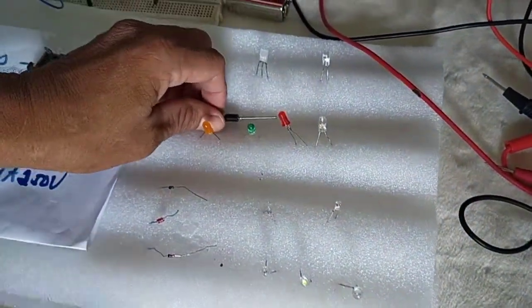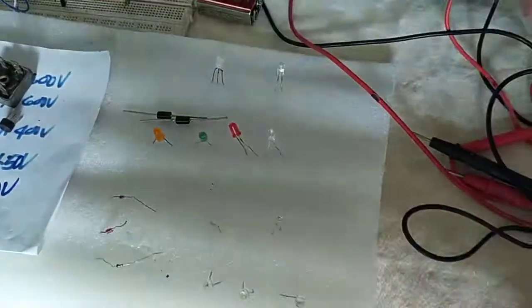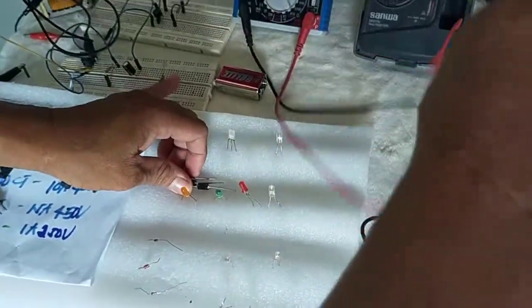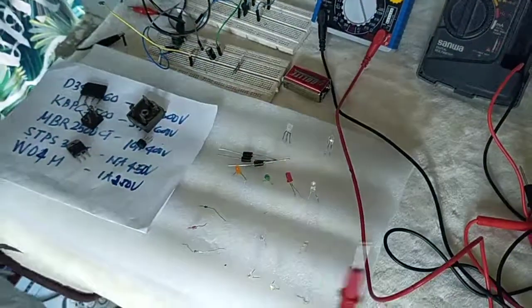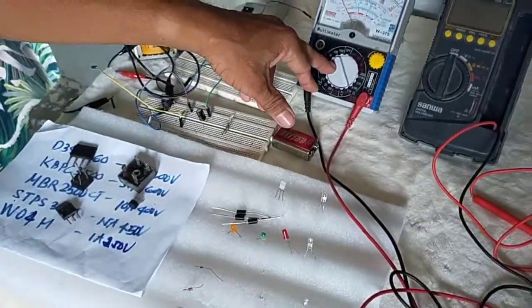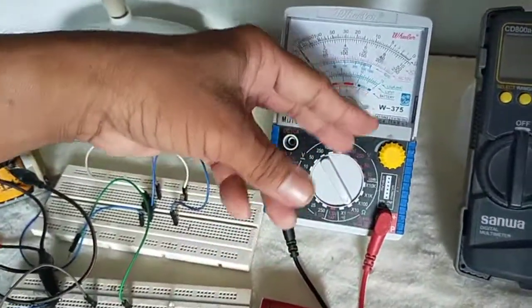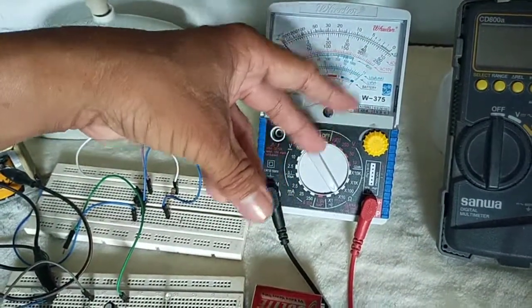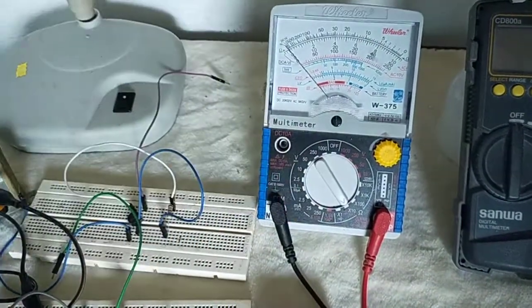Okay, we have here. Last time, you were reminded that when you are looking for the electrodes of the diode, we have to use times 10 ohms and above. You may use times 100, times 1k, times 10k, rather than times 1.